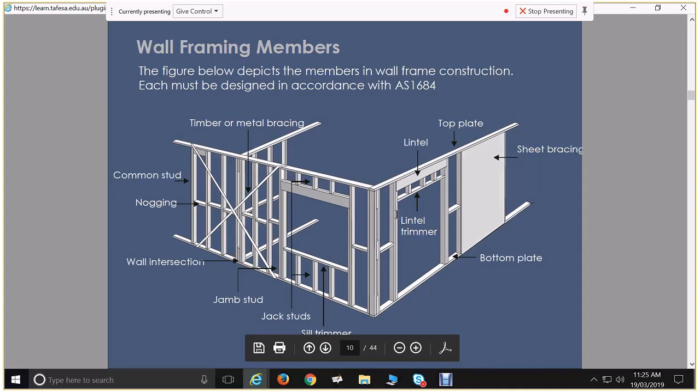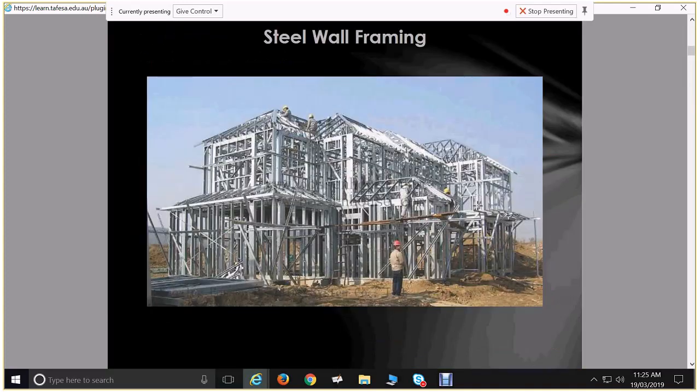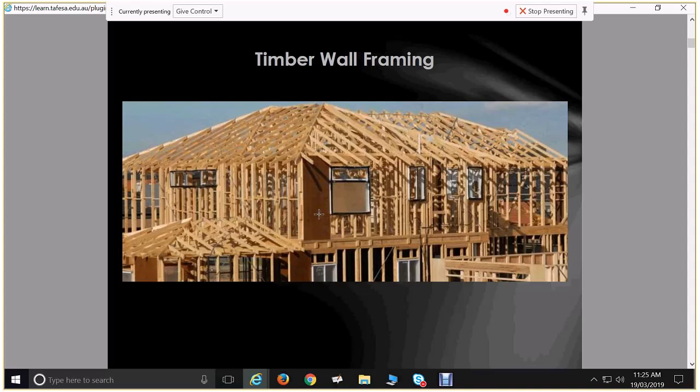What material is that sheet bracing? So that sheet bracing traditionally is hardboard. Now if I flick right back up to the first one there, that dark coloured stuff, that's hardboard. And in your timber framing code, when you go into bracing, it's got a section for hardboard and for plywood and also for the strap bracing. What it doesn't have a section for is OSB. But OSB is what pretty much everybody is using now.